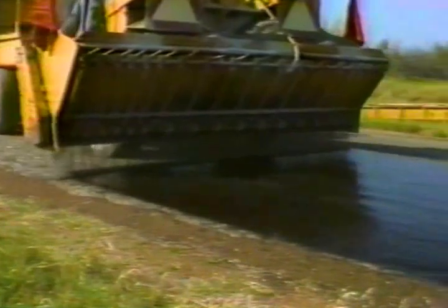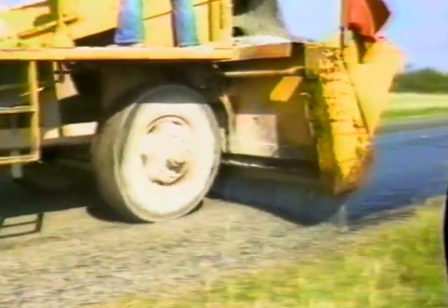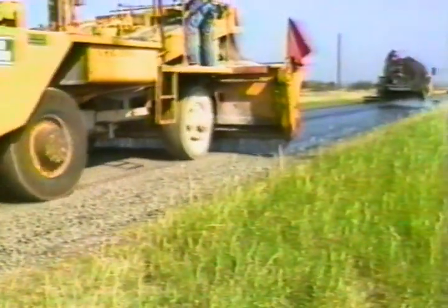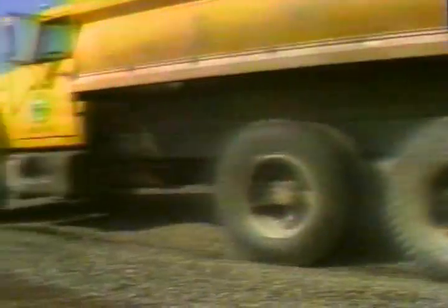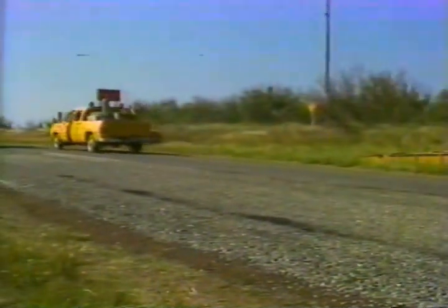This debris often protrudes through the surface after the chip application. The worst spray bar problem is revealed by this trail of binder. A serious leak in the distributor's plumbing with the bar under pressure leaves a thick pool of oil on the pavement. When the binder is applied, this concentration of oil will not be apparent. But when the chipper covers the pool with aggregate, the problem rises to the surface as the first wheel passes over it. The chips are pressed down and the oil seeps through. Subsequent tires and rolling equipment pick it up and track it.